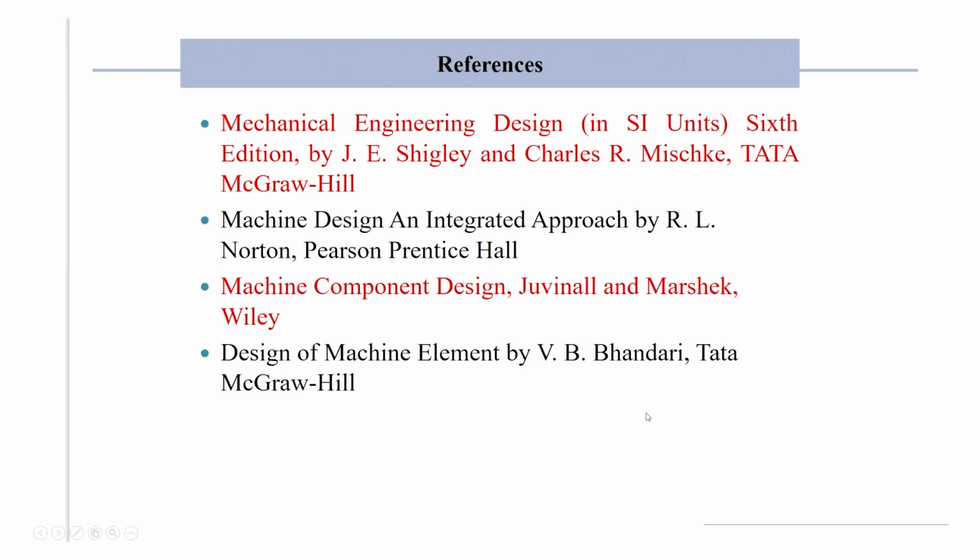And with all these selected values, we got a satisfactory factor of safety of the pinion and gear against bending and wear. Therefore, we can say that the gear is designed with module equal to 6, face width equal to 105 mm, and the material is nitralloy 135M with core hardness equal to 320 Brinell.